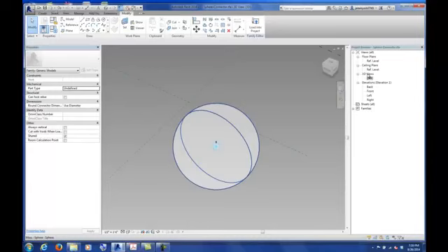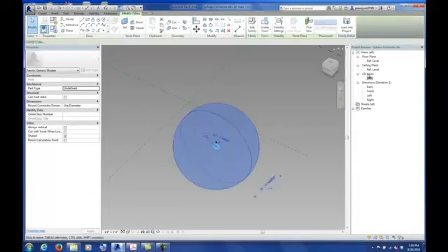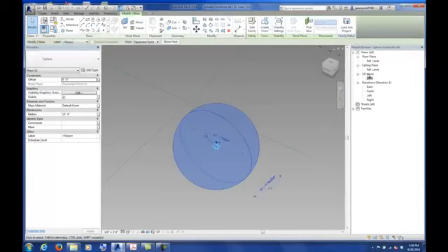Click on Create Component, and then you've got your sphere. Now go to Pick. Under your placement plane, make sure you go to Pick, and then pick that. Yep. Tab over, and now snap to the center. There you go. So everyone should have a sphere on your screen, and that's the easy way to do it, but you cannot control it. It's always going to be a sphere. If I ever wanted to control the start and end angles, I'd have to do my own sphere like we just made. But I don't need that.